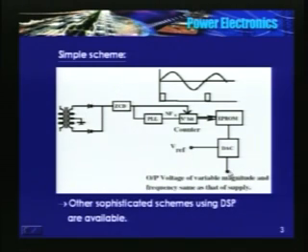So at this point the reference wave, which is also the modulating wave, is a rectified sine wave of the same frequency as that of the supply and variable magnitude. The magnitude is proportional to Vref. Now this Vref can come from either a microprocessor or a microcontroller. This is a very simple scheme to synthesize a sine wave. There are more sophisticated schemes using DSPs available. Maybe you can read the textbooks and find out.